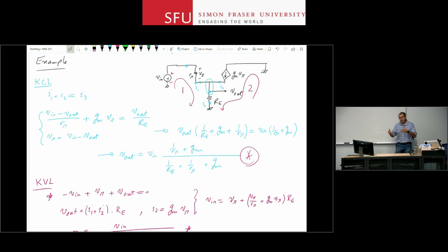And first of all, that's a little bit inconvenient. You have to open up the circuit, put the current meter in there and then do the measurement. And if you want to go through the different branches in your circuit, things may not even be possible, right? If you're dealing with a circuit that is already on a PCB, you cannot open up those tracks and do a measurement on them directly. It could be a track that is on the third layer of a 4-layer PCB. But voltages you can always measure. As long as you have a view of that track, you can put your probe in there and measure it. Because they're easier to measure, it's easier to get an insight about how the circuit works and if it is behaving properly if you're dealing with voltage signals.